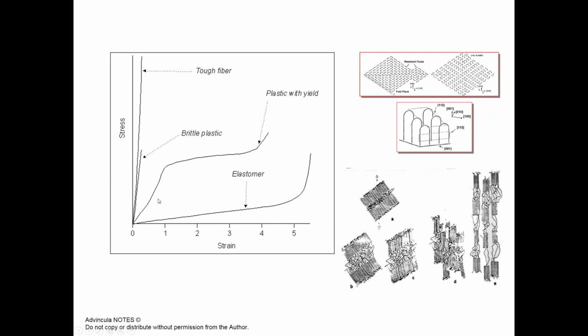And a typical plastic will show this behavior, where you have the transition from a glassy to an elastomeric phase and finally the yield point, which can be represented by changes in the distribution and the amount of amorphous and crystalline species present in a polymer. So suffice it to say, most plastics are semi-crystalline. That is, they have a crystalline and an amorphous component.